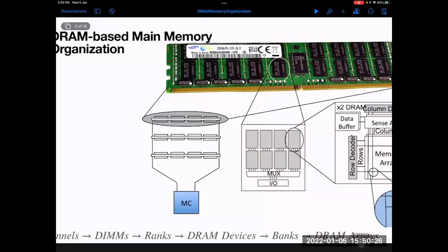But even though there are almost 200 to 300 papers on rowhammer, if you want to come up with an attack using rowhammer, you have to do experiments in a very controlled manner, because you don't know which bits you are going to flip. Even when you perform a rowhammer, you cannot say, okay, I'm going to flip bit 1 or bit 2. You have no idea which bits are going to be flipped. That is the drawback with rowhammer. Even though it's interesting work, from the side channel point of view, Spectre and Meltdown are the predominant attacks on microarchitectures or processors, more than any other techniques.